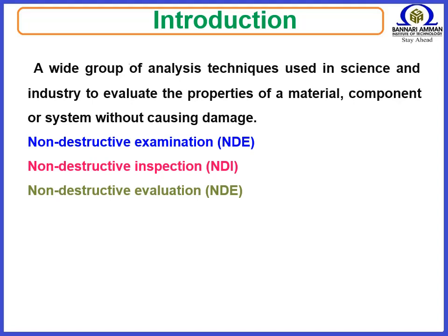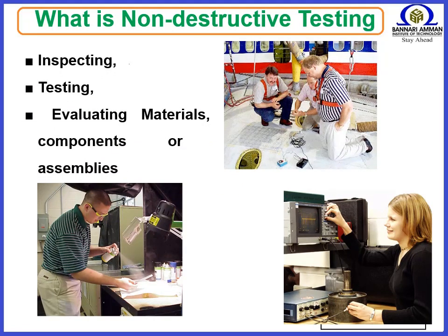Typical examples are found in aircraft, spacecraft, shuttle, motor vehicles, pipelines, bridges, trains, power stations, refineries, buildings. Non-destructive testing, NDT, is an interdisciplinary science that uses many different methods to evaluate the properties of metals, parts, or assemblies without causing damage to the tested part or assembly. Because no damage results from these testing techniques, it is often done as part of the manufacturing process to determine if any flaws are present or created. It is also often used for product evaluation or during failure analysis.